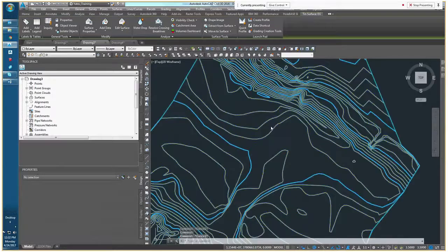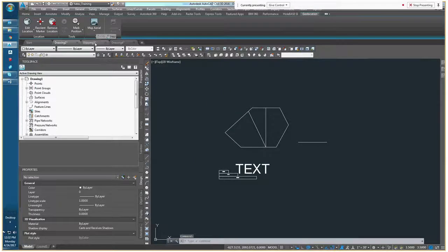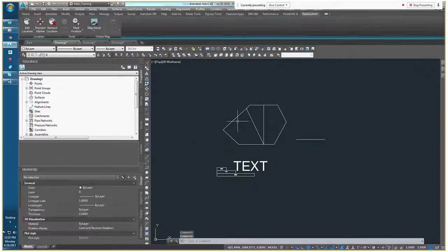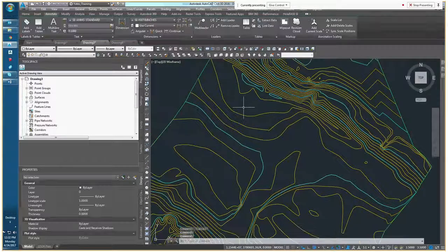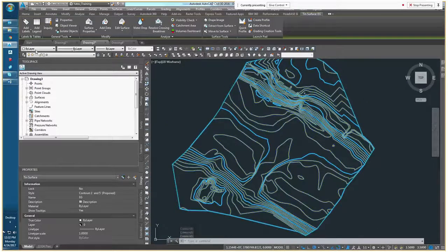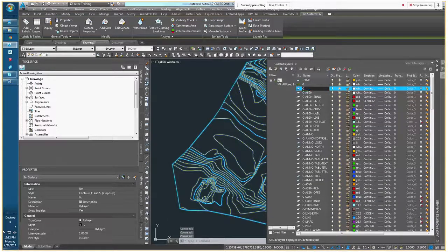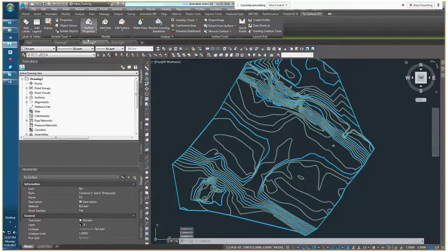This surface, sorry, let's go to the actual Civil 3D template. This was the drawing one. Drawing 3 was the one that started with the detailed DWG template, and so the surface itself did not end up on the appropriate layer. And so to maintain the NCS CAD standards, I would start that with C dash. I could do surf, I could do 10, I could do topo, but I'll call that C-TOPO-EG, and then I could put that on the appropriate layer.